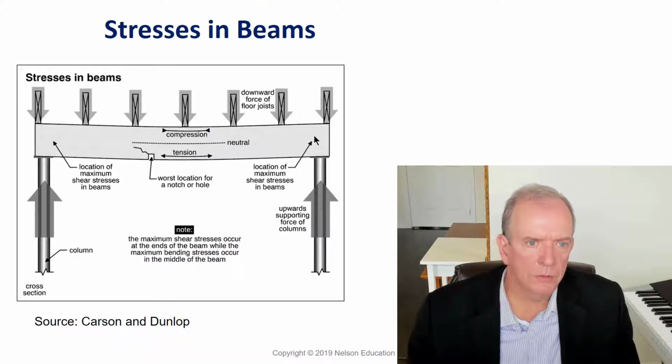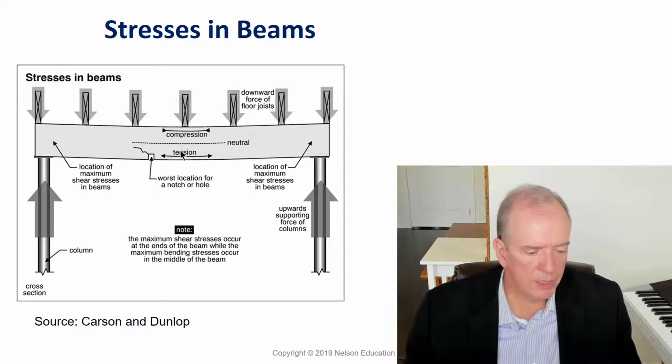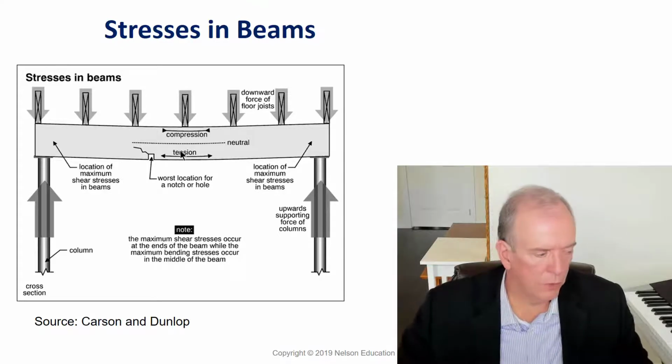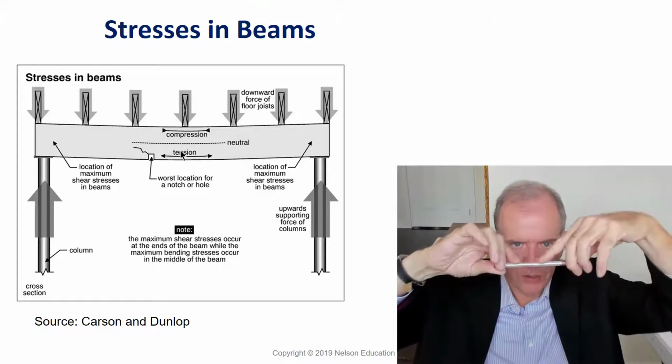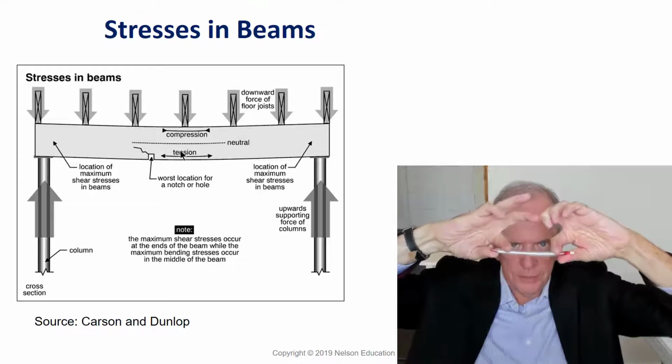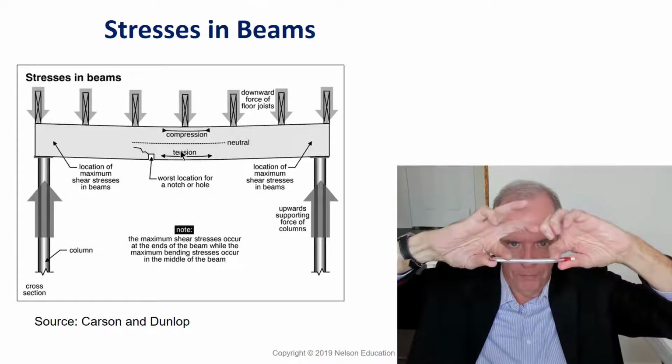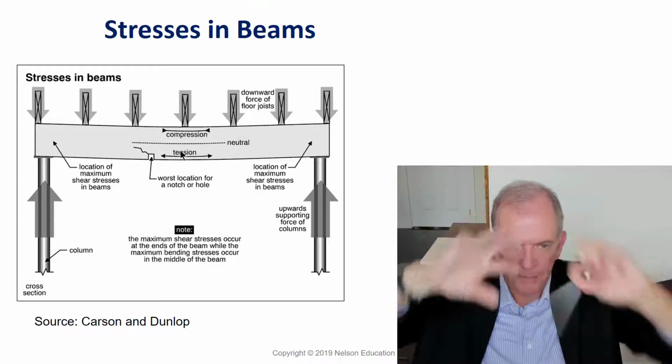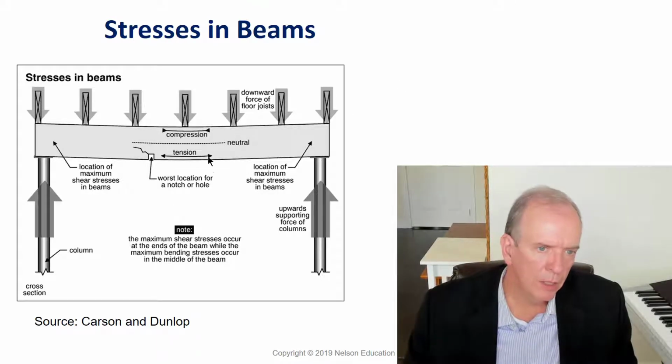So when we talk about beams and stress points, when you've got a floor resting on top of it, we've got this situation where a load is coming down on top of something, and when it pushes down, right? As I push down on this, you've got compression on the top and tension on the bottom. So in this image, as the weight comes down on this beam, the bottom is under tension and the top is under compression.